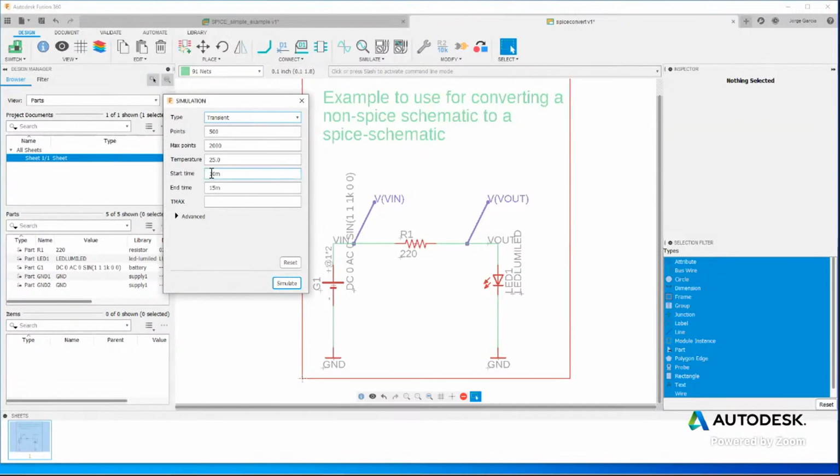Okay. One thing that we typically recommend with simulation, if you're doing transient behavior of things that oscillate or that are being subjected to an oscillatory stimulus, is to look for about 5 to 10 cycles. If you have a long time range, it can be difficult for the simulation to converge and to give you an actual result.